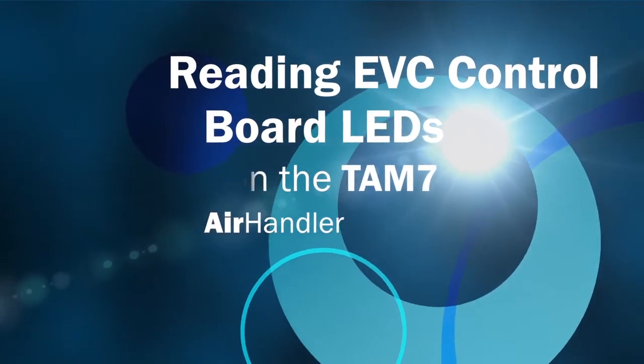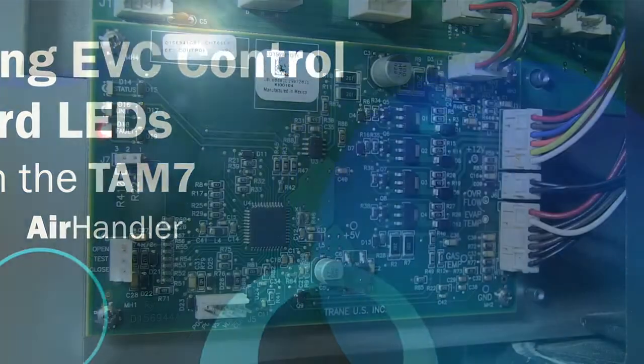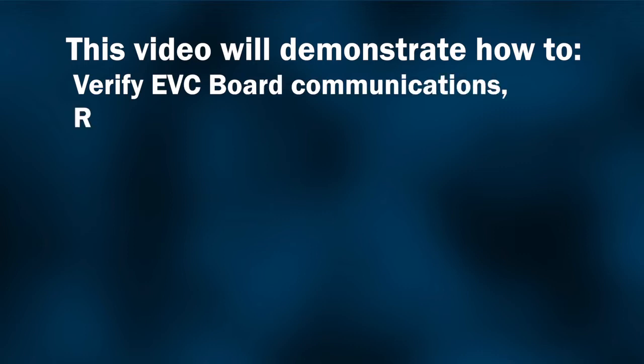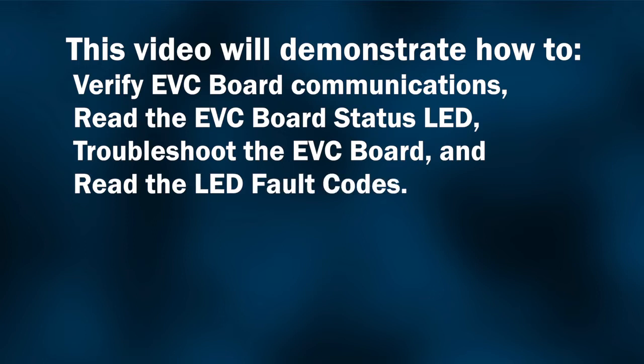Reading the Electronic Expansion Valve Control Board LEDs. In this video, we will look at the LEDs on the TAM7's Electronic Expansion Valve Control Board, or EVC. The goal of this video is to demonstrate how to verify the EVC board is communicating, how to read the EVC status LED in a properly operating system, how to troubleshoot a non-communicating EVC board, and how to read the LED fault codes on the EVC.